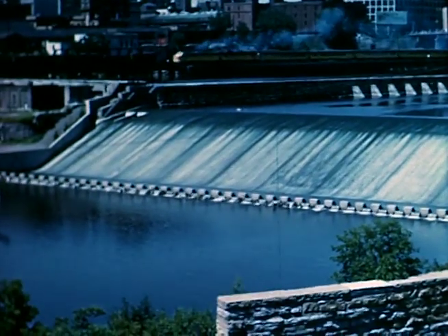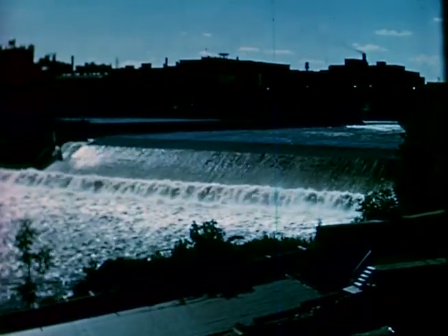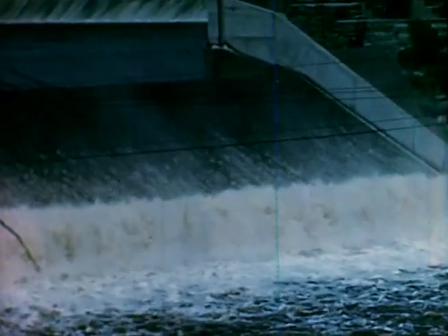Here, a turbulent river flows over a dam. A boundary layer originates on the concrete surface at the top of the dam, becomes turbulent, and thickens until it reaches the water surface where it becomes visible, because the small, intense eddies of the boundary layer turbulence entrap air from the atmosphere. The original river turbulence is invisible because its eddies, which originated on the riverbed far upstream, have decayed.